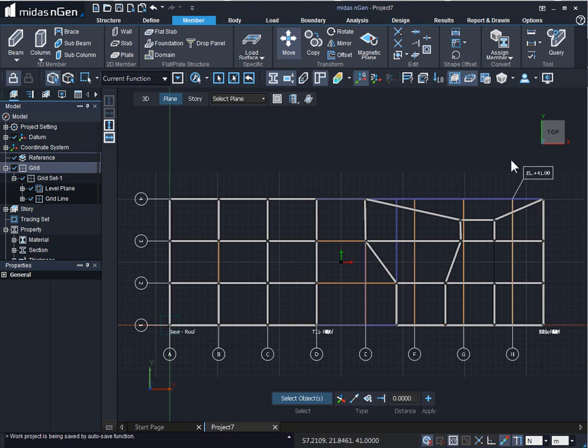In the similar way, we can perform the copy command. Select a member by using select curve or edge, drag the direction to measure the distance automatically or provide the distance by ourselves as -4, let's say, and apply. This is how we got our member copied.